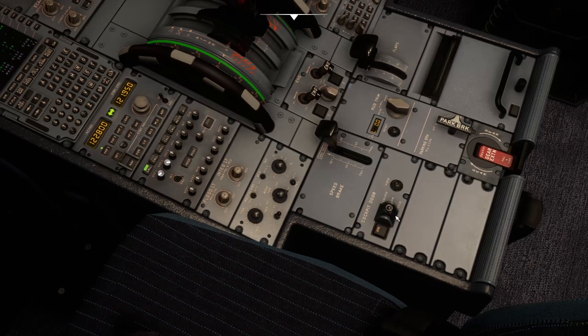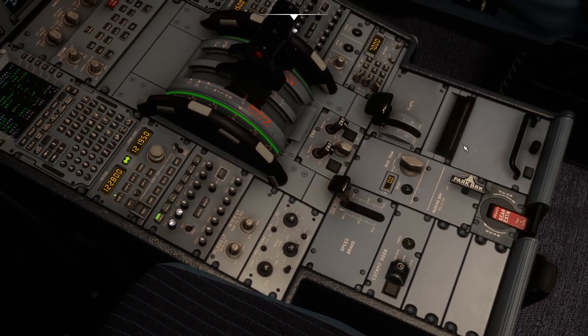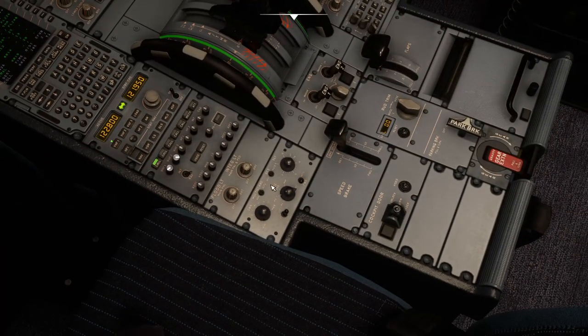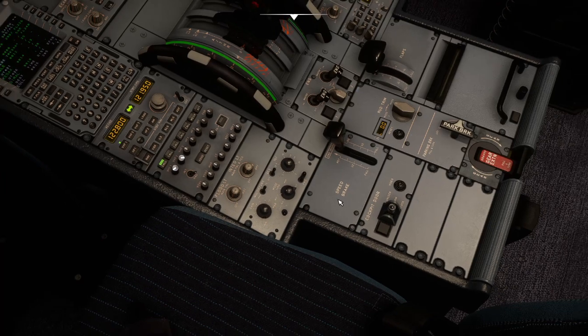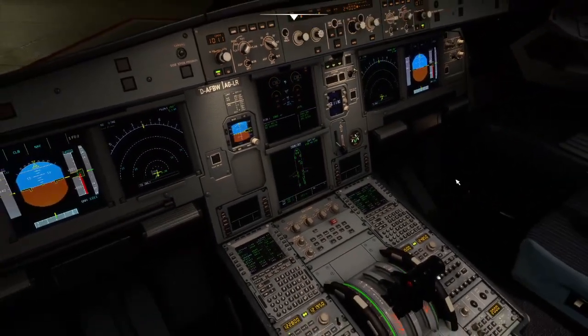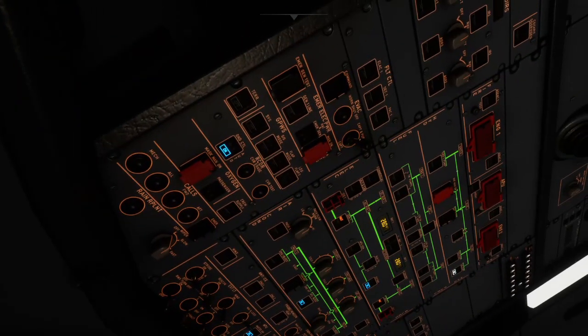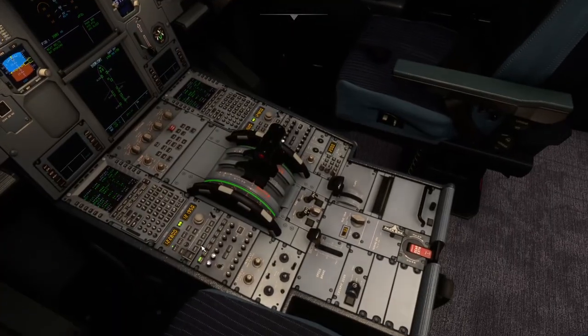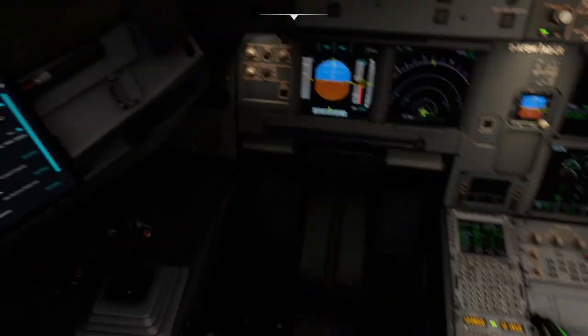A couple more things here. If you're going to go and get it, you could lock your door. Give yourself a valid transponder code, something like that. Put it in TA/RA, and auto on the transponder. Make sure I don't get the wind shear system complaining to me later. And we are pretty much looking good to go. Overhead panel is all set and looking reasonable. Beacon can come on, mission to auto.